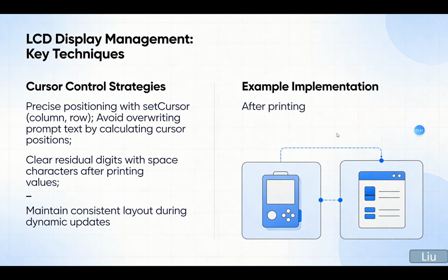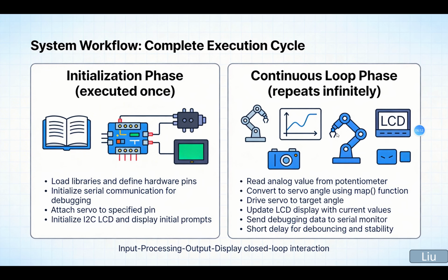Okay, so the LCD display management key techniques: fix position with setCursor, avoid overwriting prominent text by controlling cursor positions, and clear residual digits with space characters after printing values, and maintain consistent layout during dynamic updates. So the system workflow, complete execution cycle.